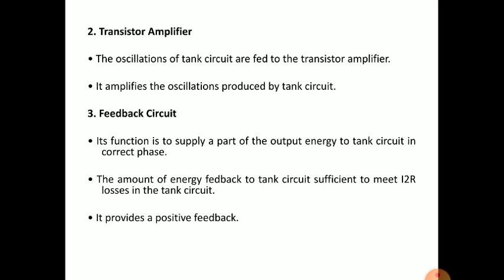So the next point is it amplifies the oscillation produced by the tank circuit. Now see the feedback circuit. Its function is to supply a part of the output energy to the tank circuit in correct phase, that is, in phase signal.